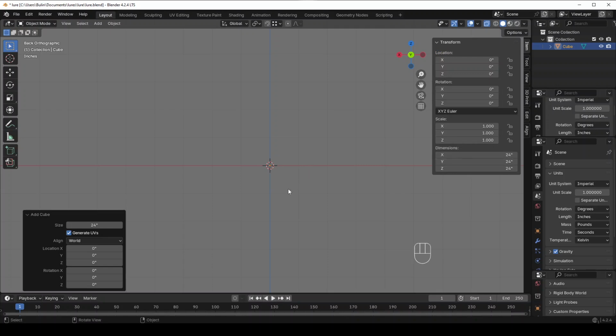And right here, the axis that we are working on for length is X, which is the red axis. So make sure up here that you are looking down the Y axis. Y will be our width. So click on the positive Y, not the negative Y.